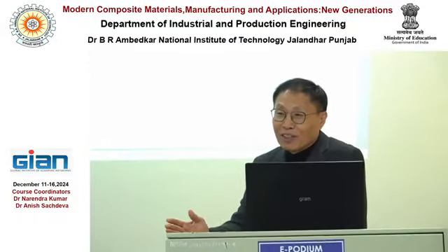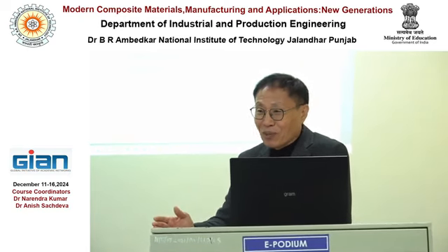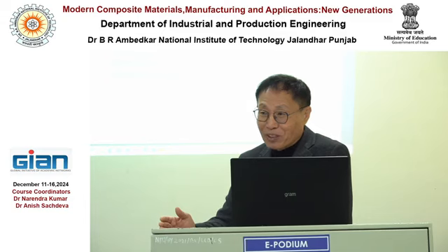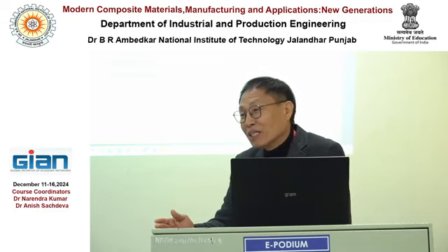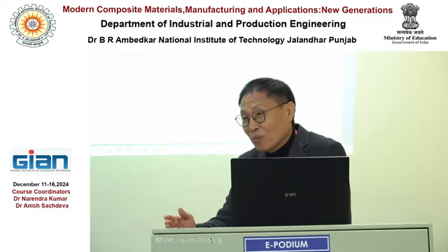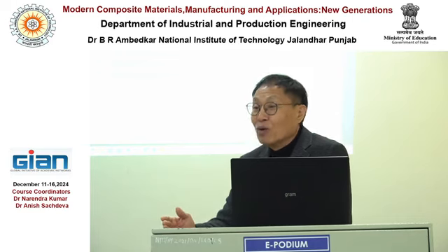But VARTM or hand layup is not possible. RTM is possible. It is because compaction pressure and temperature control are the key issues to achieve a higher volume fraction.